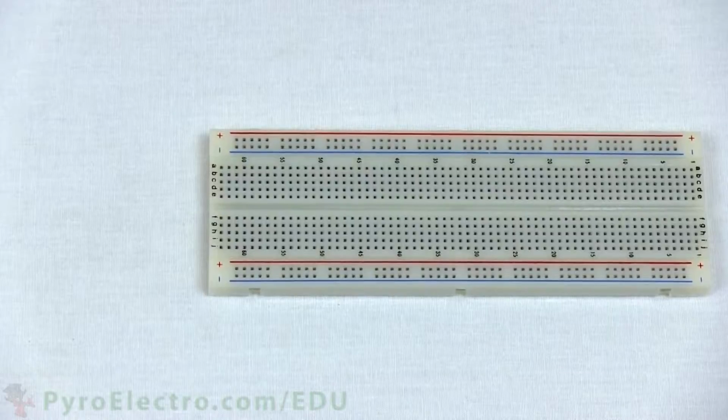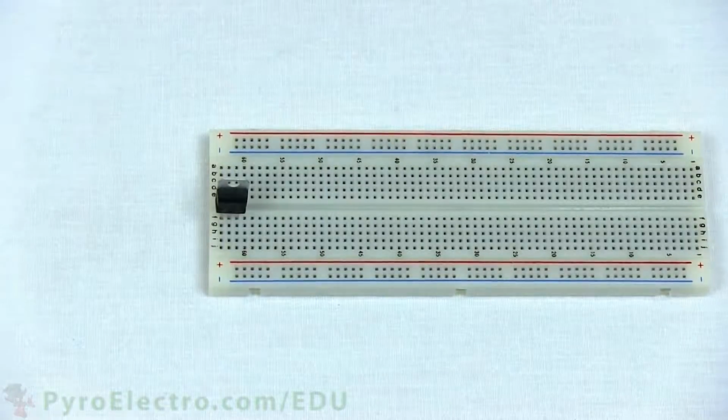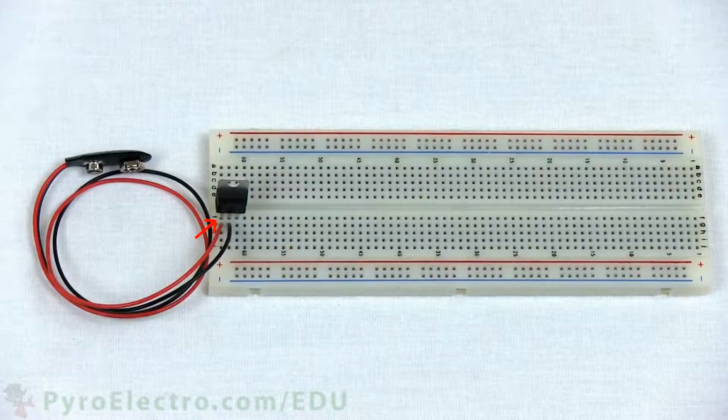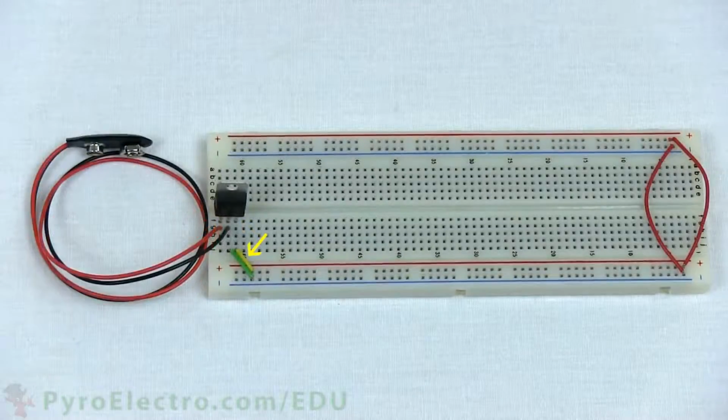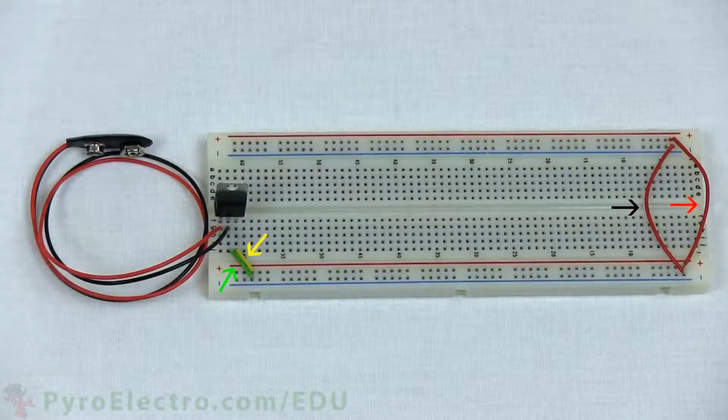We're going to want to run everything off of plus 5-volt power, so we'll use a 7805 voltage regulator at the top of the breadboard. Here, pin 1 connects to the plus 9-volt connector's input, the red wire. Pin 2 connects to the plus 9-volt connector's ground, the black wire. And pin 3 is the plus 5-volt output from the 7805. We'll connect the 7805's pin 3 to the power bus line with a yellow wire, and pin 2 to the ground bus line with a green wire. 2 red wires connect the plus 5-volt power and ground to a second bus line on the breadboard.